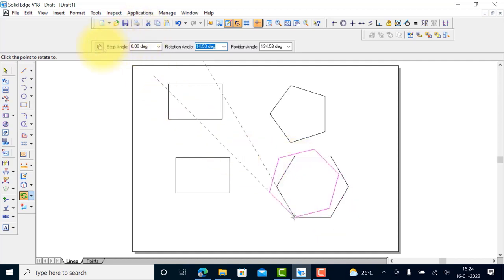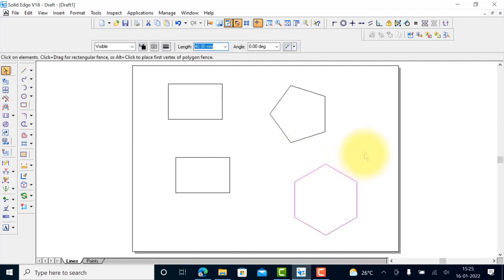Here this is already switched off, so you can make this vertical. When you get that vertical symbol, just click the mouse, and you got this in the vertical position. Now this is vertical, so minus 90 or 90 shows that it is vertical. So you got the hexagon rotated and it's making 90 degree. Two of its parallel sides are perpendicular to the XY line.